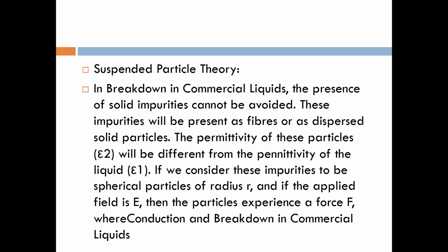So remember one thing: the suspended particle theory is due to the presence of solid impurities. These may be in the form of fibers or solid particles. When considering the suspended particle theory, the permittivity of the impurities and the permittivity of the liquid itself are very important, so that we can find out the force experienced by a particle in the conduction in the material. In the next lecture, we will continue with suspended particles, then go on to the cavitation and bubble theory, and then the trace oil volume theory.